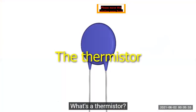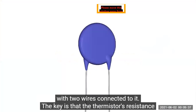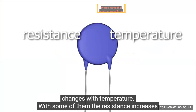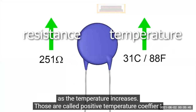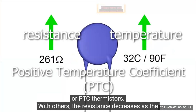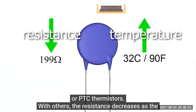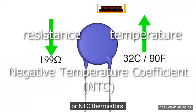What's a thermistor? A thermistor is usually a ceramic or polymer material with two wires connected to it. The key is that the thermistor's resistance changes with temperature. With some, the resistance increases as the temperature increases. Those are called positive temperature coefficient, or PTC thermistors. With others, the resistance decreases as the temperature increases. Those are called negative temperature coefficient, or NTC thermistors.